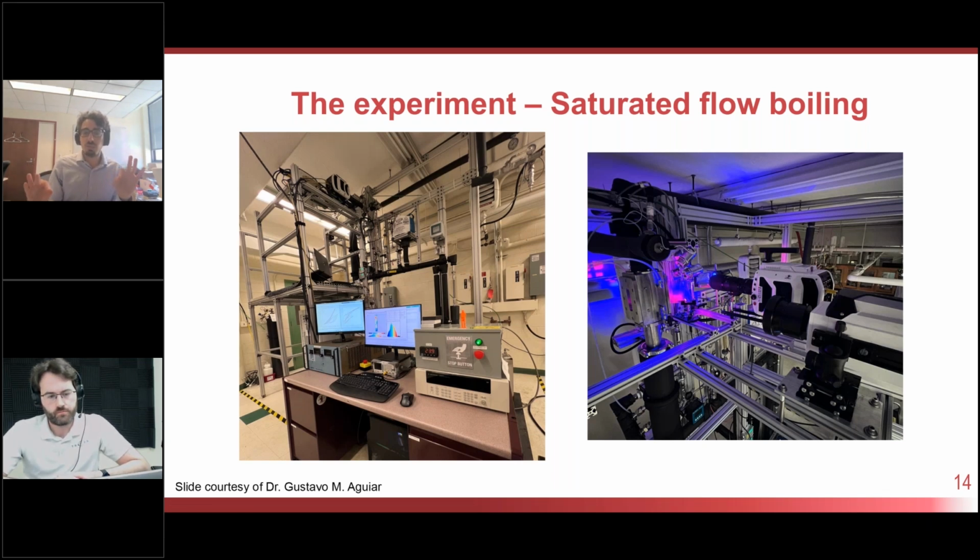In that case, it's a little different because what you're measuring is the temperature at the back of your foil, which is very thin, and so you can consider it to be isothermal. In our case, we have the sapphire, which of course has a certain thermal inertia, and then we have this very thin ITO coating on top, which we use to measure the temperature.